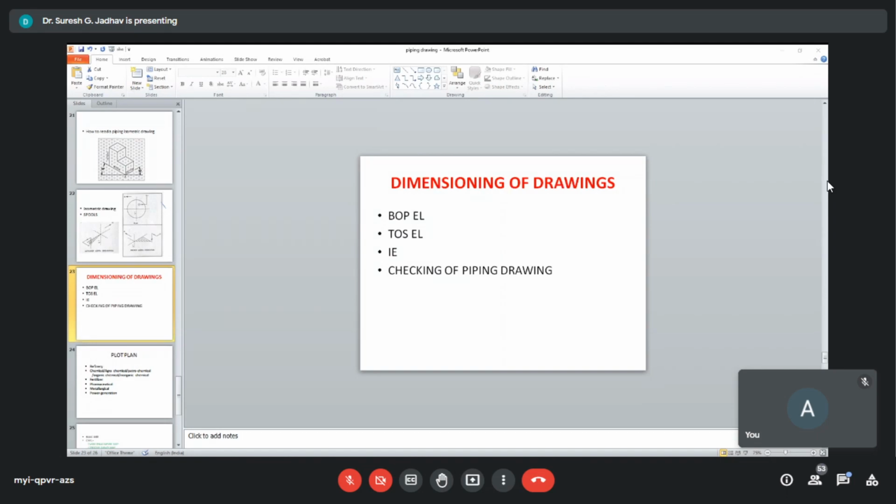Location and identification of all instruments, requirement of upstream, downstream, straight lengths, and insulation requirements as per P&ID's, process and instrumentation diagrams. Piping arrangement against P&ID requirements such as gravity flow, seals, etc. Possible interference and correctness of scale in case of general arrangement drawings.